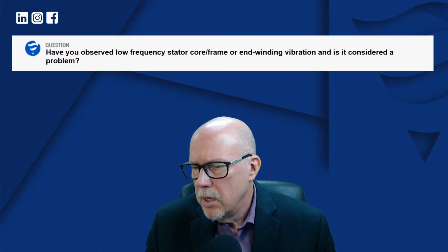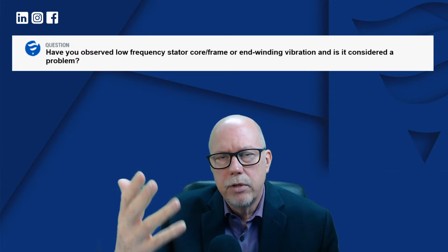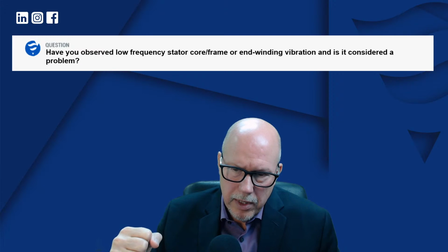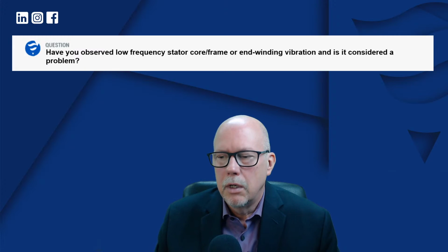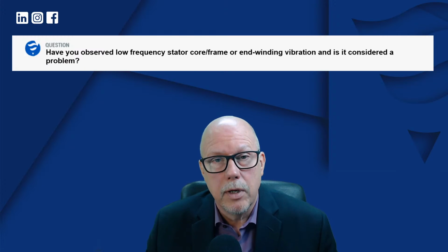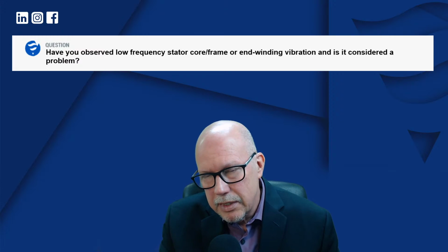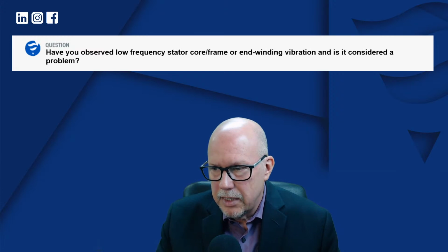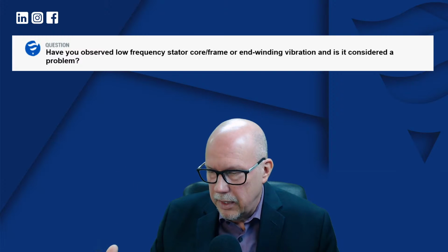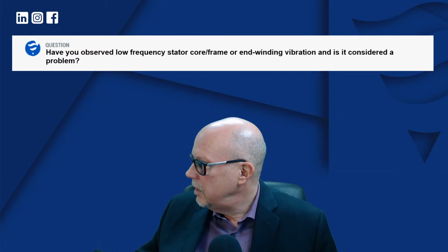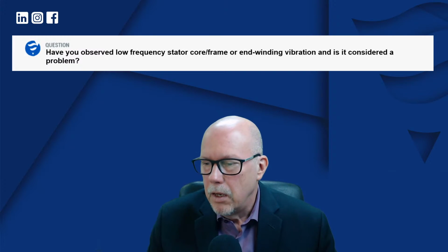There's no issues. But where you have issues is in the case I mentioned previously, where you could see the frame and the core were actually impacting against the foundation, and that's a serious problem. And that won't show up necessarily as low frequency activity. You will see some, but it's actually showing up as very high frequency, as I said, repeatable, and it's periodic. It's like a beating or a modulation that shows up. That's very easy to see.